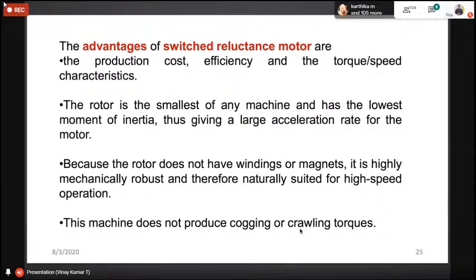If acceleration time is more, heat dissipation time is more, and the machine will get damaged. Insulation will lose its property in this period, so you have to take care of insulation also. That's why, if acceleration time is less, we can save a lot of electrical energy and reduce the heat dissipation from the winding.